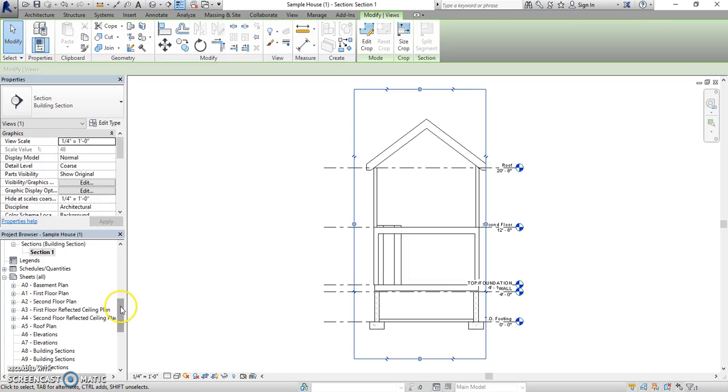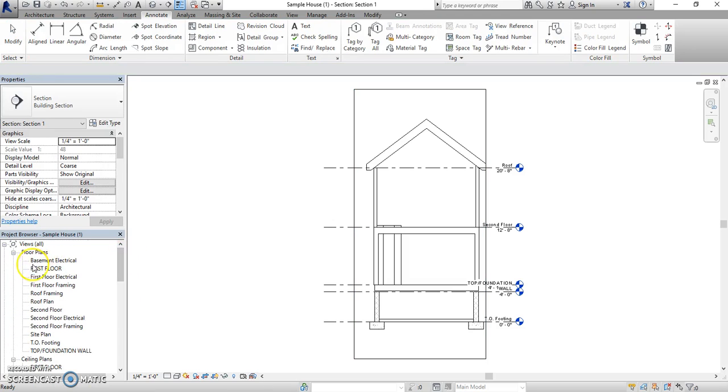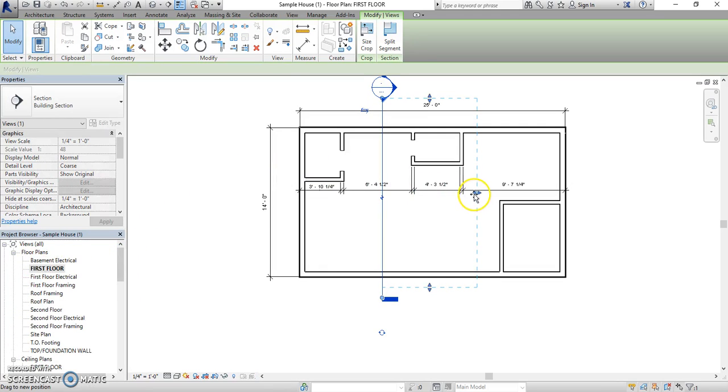I'm going to reduce the depth of view even more. I'm going to bring my depth box in so that I don't see anything. I don't see any of these interior walls. All I'm going to see is the exterior wall cut here, the exterior wall cut here, and the floor and everything else on this cutting plane. Only if I were to take a slice vertically through the house, I'm only going to see everything on this plane and back as far as this depth line will go.